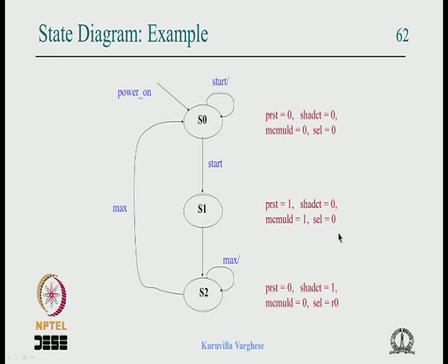As far as the figure is concerned it will be much neater, but when you develop a next state table or output table or write code to do this, you can miss that point. Don't do that, you will get into a lot of trouble. So I don't suggest that you do such a thing. There are clever ways to circumvent that problem by initializing some default values in the code, but it's not a very good idea. It is better you write explicitly what the outputs are.